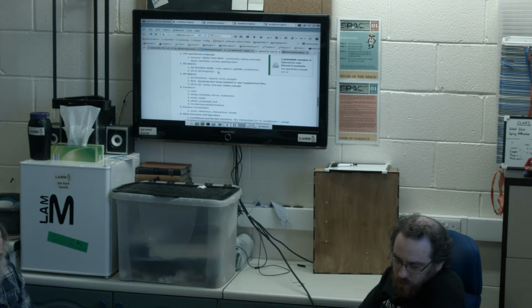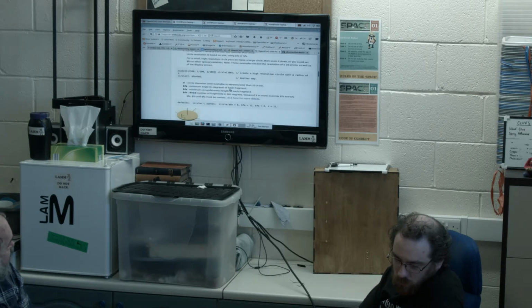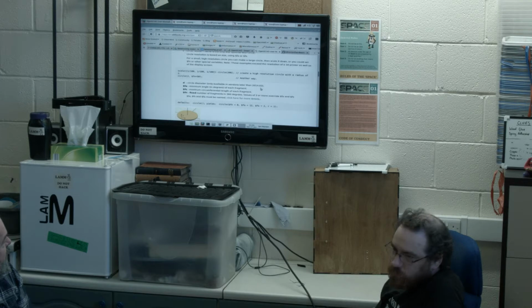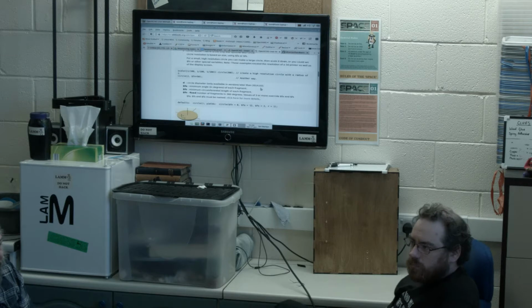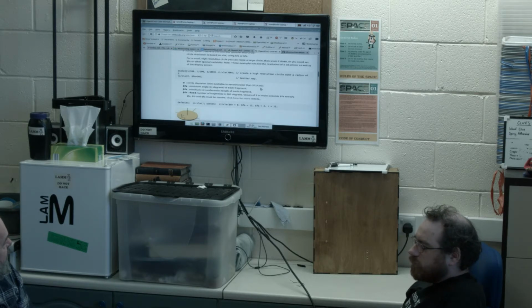I think the perfect one for perfect circles would be 360, because I think it's the number of segments per angle. It's in degrees. I'm probably talking out of my ass, but there you go. Minimum angle: FN is the minimum angle in degrees of each fragment. So if you put 360, you'll have 1 degree. If you put 180, you end up with a line.